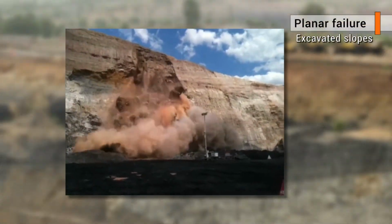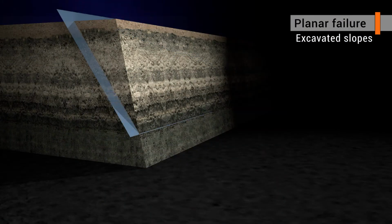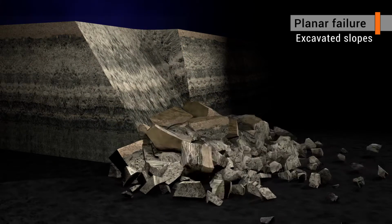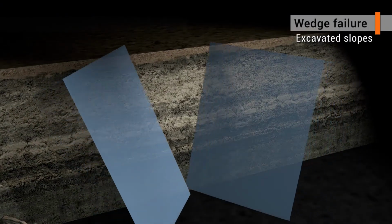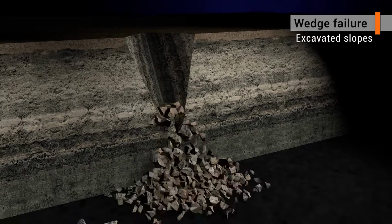Planar failure. These types of failures occur where a block of rock slides along a single defect that dips and daylights in the excavated face. Wedge failure. Wedge failure occurs where two continuous planar defects intersect and daylight in the excavated face.